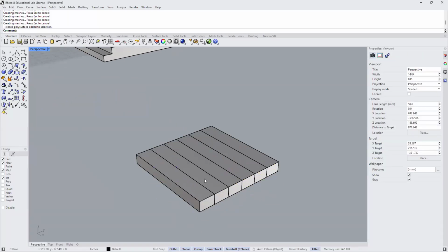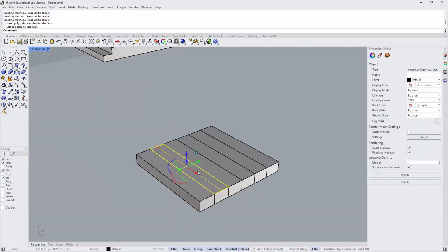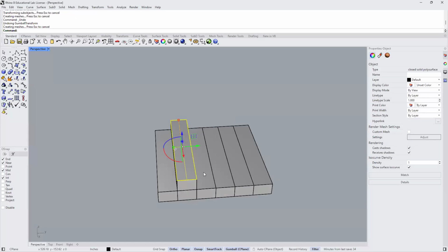So now what I'm going to do is, sorry, I'm always orbiting. I will go ahead and Control Shift, click on this surface. I will take it up 8 inches. And I did this before, and I'm glad I made the mistake again. Notice what's happening. I can't just move that because everything else is connected, so I need to extrude it. So let me undo that and click on the blue dot here and go 8 and enter. There we go.